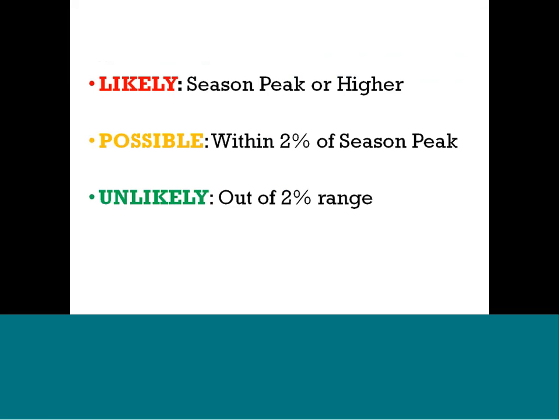So at the beginning of the year, we set a threshold for likely based on what we've seen in past years, and then inevitably we tend to cross that at some point, usually in late July, but it could come earlier. So likely is you probably want to do what's called load shedding. That's when you would actually take actions in your building to reduce demand, reduce your load for the peak hour.